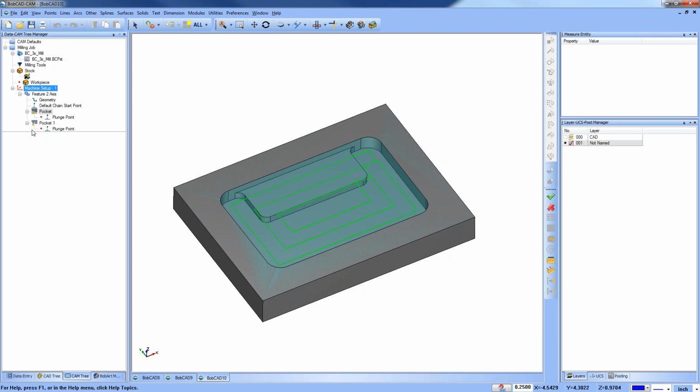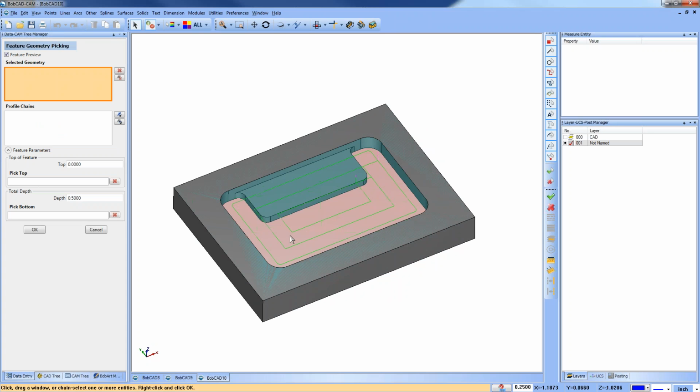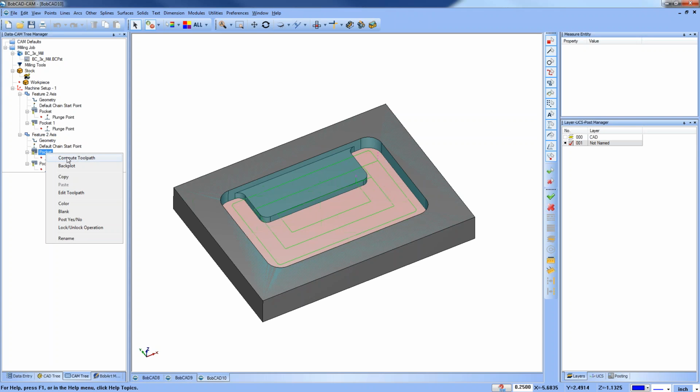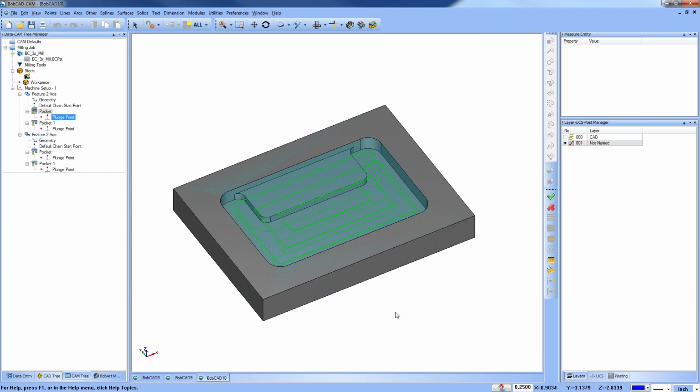And then once you've done that, you can come in here and select that bottom face and machine to that face. So there's a lot of approaches for this, but if you have a multi-level here where you have a flat like that, that's coming out either three-side or some kind of land, you may pocket down to the top of that boss that's there, and then you may go in and machine from the bottom there, if that makes sense. Again, just using some of the different tools that you have. You may come in here and just machine this area too.